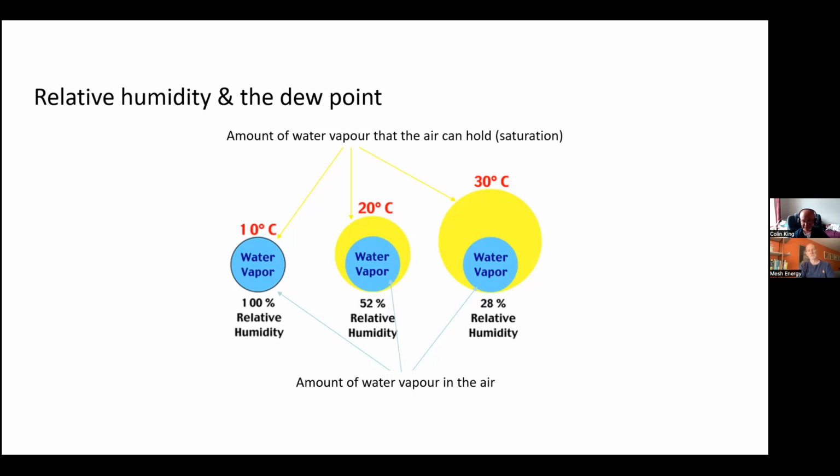That's where people need to be able to heat their properties, which is why we do things like insulation, draft proofing, other simple measures to make those buildings more cost effective to heat. Because obviously if you reduce the amount of heat loss, you end up being able to heat the building more cheaply, which means that people in fuel poverty are more likely to be able to create an environment where the relative humidity is between 50 and 60%, which is where we ideally want them to be, but then taking into account the context of whether they have any disabilities or mobility issues or their age or predisposition to conditions. It's a complex issue to maintain that, given how people move and live and how the building performs.